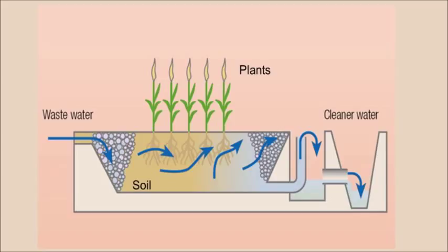Regarding the process, first of all, the wastewater coming from the sewage system flows slowly into the constructed wetland through the sandy substrate, which mainly serves to filter out solids. The filter consists of a large vegetative planting, in this case rushes, whose roots in the sand are fed by the wastewater. The nutrients in the water are absorbed by the plants, which store them in their tissues as they grow. The treated wastewater is then discharged at the end to a receiving water body.